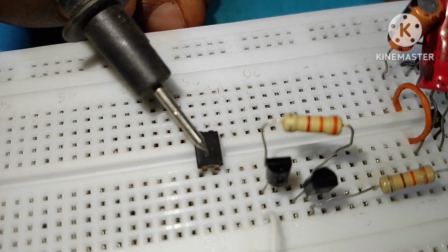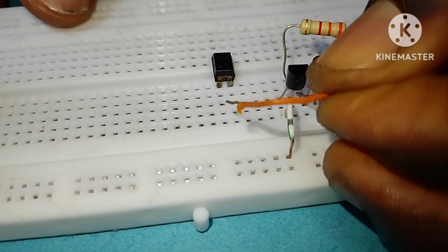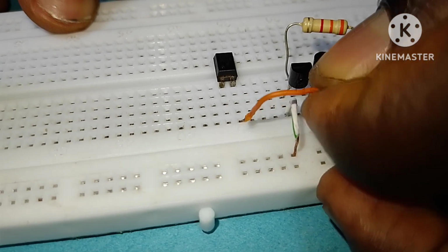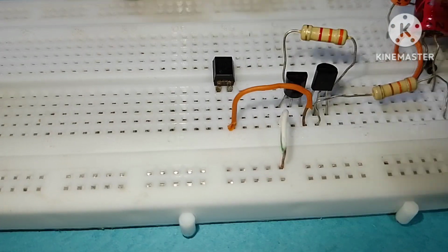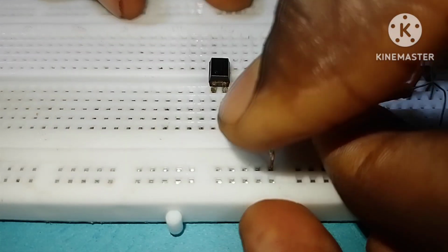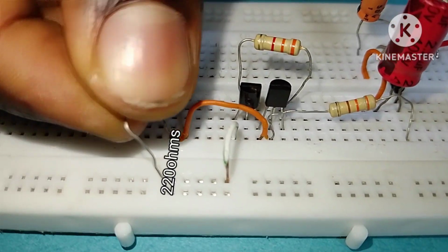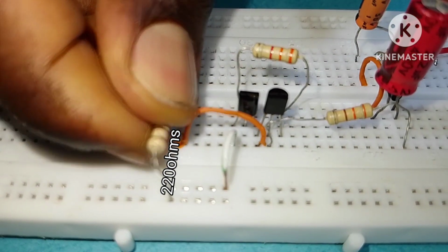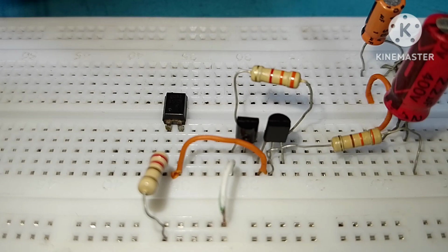That's our input voltage; the dot signifies the anode pin, and then the second one is the cathode pin. With the cathode pin, place your jumper wire to the collector pin, and place a 330 ohm resistor to the anode pin and to the positive VCC.